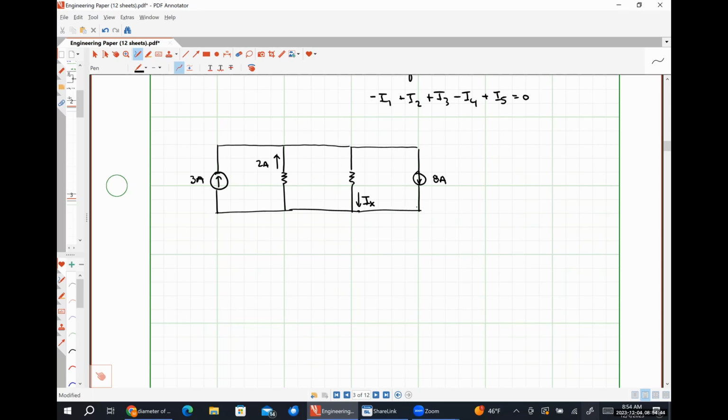So in order for us to apply Kirchhoff's current law, we need to decide on a node to apply it at. The circuit that I've drawn has exactly 2 nodes. What's commonly called a single node pair circuit, which just means everything is connected in parallel, right? So everything is connected between the top node and the bottom node. So do we want to apply KCL at the top or the bottom? Random. Top or bottom, completely arbitrary. Pick. Top, okay?